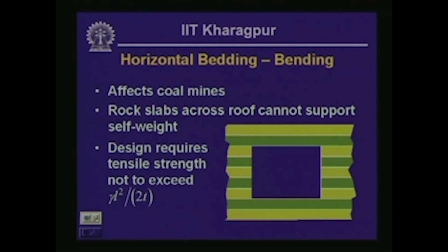So, basically what is preferred in this particular case, and that is often adopted in design, is a square cross section of the tunnel. Because if you have got a square cross section, then the slab near the tunnel crown, the roof of the tunnel, is not likely to lose any thickness, and as a result the stability is going to be much more.